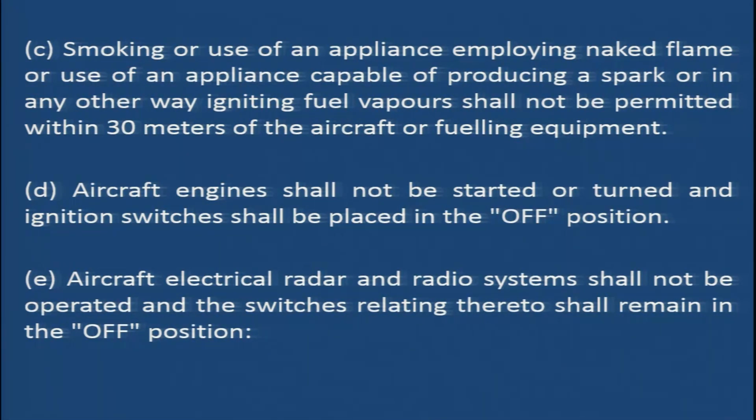Aircraft engines shall not be started or turned, and ignition switches shall be placed in the off position. So, during fueling all the ignition switches should be kept in the off position, the engine should not be started, and we need to observe these precautions.